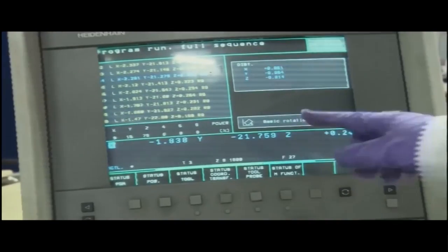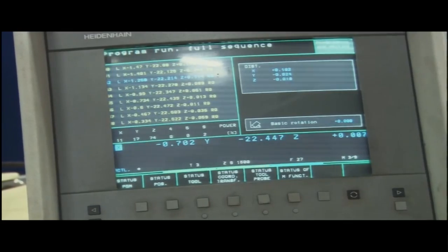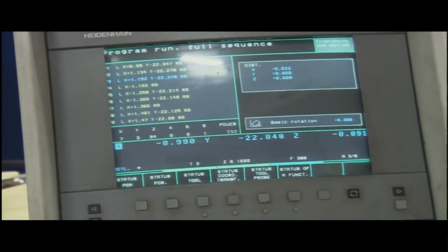Now, step by step the codes are moving, see 0, 9, 50, the codes are moving, the movement is now going on X and Y direction. So, the tool is not moving, the Z axis is almost fixed once the plunge in has happened and cutting has started. Now, X and Y direction are all taken care by the machine table.